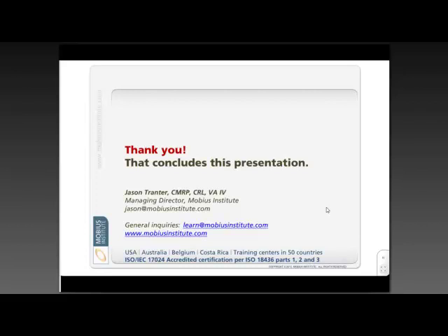It's called the PF interval. You know, P, potential failure, F, functional failure. Between those two points, the point where we can detect it and the point where that machine should no longer run, it's no longer performing its function, we need to take at least two measurements. We'd like more. The earlier we can detect it puts us in a strong position to take the desired action. The right person doing a good job with the right tools, with the right parts for the minimum cost and the highest level of safety.